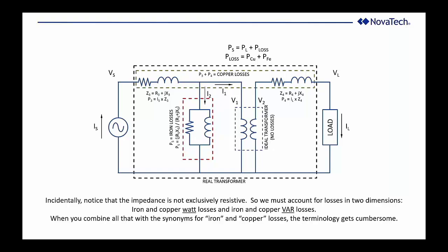And usually for a single phase, it's easier to look at the line-to-neutral voltage. On a three-phase transformer, most of the values and the ratings are given in phase-to-phase units. So on the one hand, there's a root-of-3 multiplier to deal with. On the other hand, there's a divide-by-3 factor that we have to be concerned with. These are the reasons why people generally, I find, have the impression that loss compensation is difficult. It's more a function of terminology and keeping things straight than it is the underlying theory that goes into the losses and the compensation for those losses.